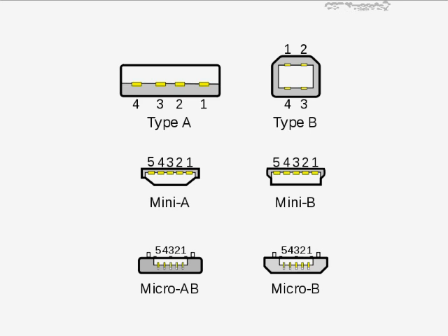And then here's simply a list of the different types of connectors that you might see. The type A we already looked at, the type B we also already looked at, and then we also looked at the mini B that we have right here. There is also, just FYI, a micro B. This is something that's even smaller than the mini B in many cases, at least it's slightly narrower. And what this does is allow us to connect to other types of devices. For example, I know a lot of Bluetooth headsets connect to the micro B as well. There's also a micro AB and a mini A, but I've rarely seen those in any implementation. Normally, it's this whole L section right here that you'll see in practical use.